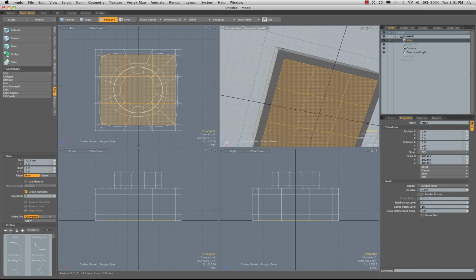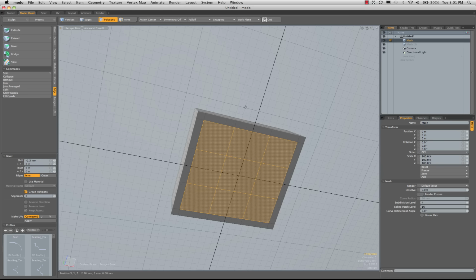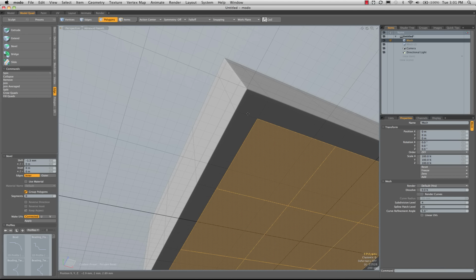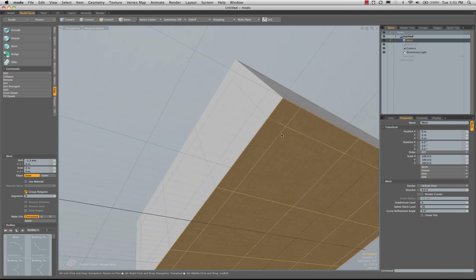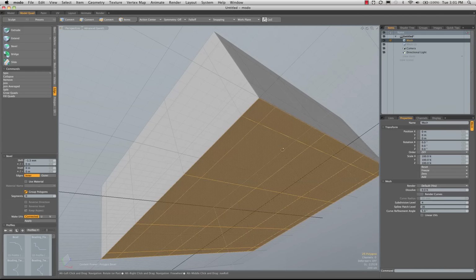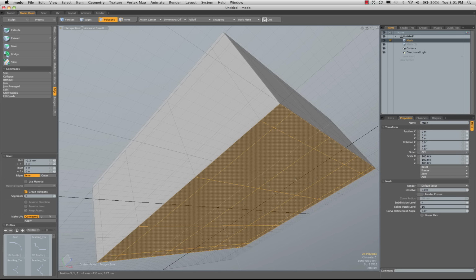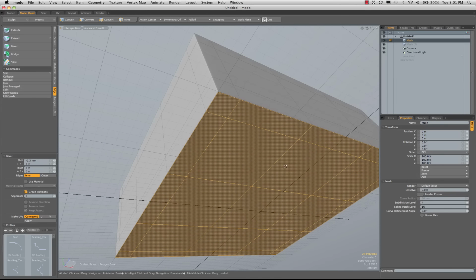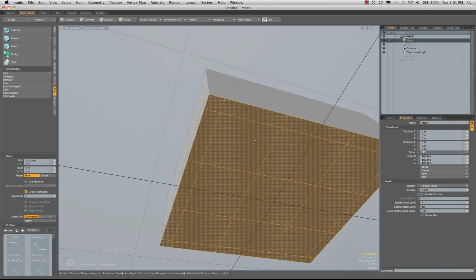Now, one important thing to remember here, and this is true of a lot of subdivision surface models, is that if you have a couple of edges defining another edge, and you can use them when you go on to make more bevels or attach them to other things with the bridge tool, if you can reuse those same ones, you're generally going to be in pretty good shape. So we're going to use these.